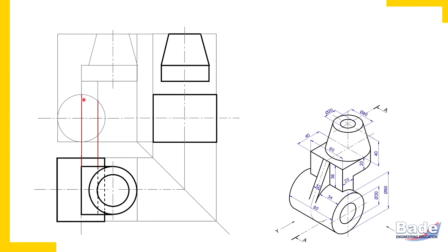Now watch here. Where is this plate in the top view? If I ask you, you should show me this entire rectangle. And this rectangle is dotted under the U-shaped plate, hidden under the U-shaped plate. So this entire rectangle is dotted. But out of these four edges of the rectangle, these three edges are overlapping with the earlier drawn visible edges. But the entire rectangle which is dotted is present here.